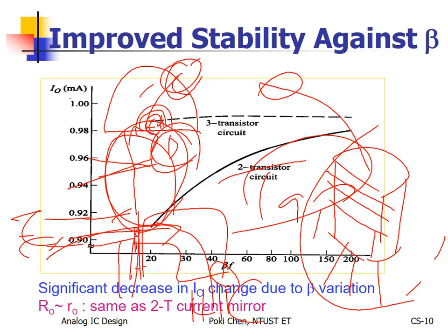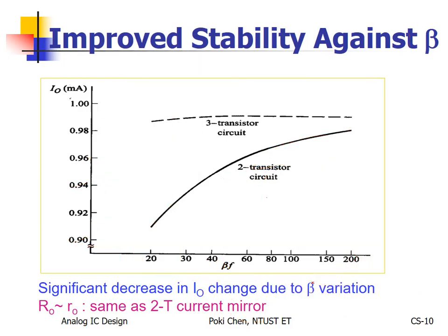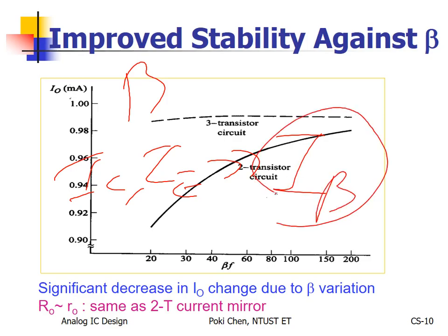It doesn't make any sense, right? So to reduce the leakage at the base, the base needs to be very, very small, I mean in thickness. Okay? And again, the overall area for base, because it's really, really thin, means what? Again, the standard deviation. So that is what you need to face. Anyway, the base needs to be really, really thin to reduce the current leakage. So very small current will flow through B. That is what we need, because IC or IE should be much, much larger than IB. It means what? Beta can be as high as you expect.